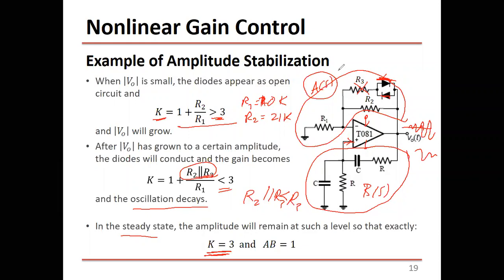So the gain here is a constant, and it is 3, a positive 3, right? And this one has a transfer function gain of 1 over 3. So this is a positive 1 over 3. You cannot have this as a negative. So the gain here is 1 over 3, and the gain here is 3. So the overall loop gain is 1. So we don't have any negative signs here, okay?